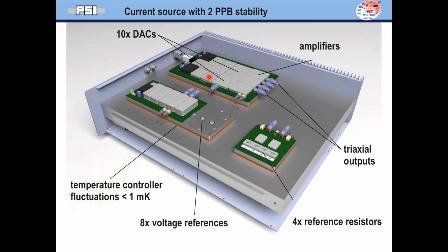The materials have to be chosen in a special way. If something has a too high conductance, for example, the material of the printed circuit boards, then you get small currents through the printed circuit board where actually there's no trace, which at the part per billion level could affect the current that you're generating. Okay, and yeah, well, this is a nice project.